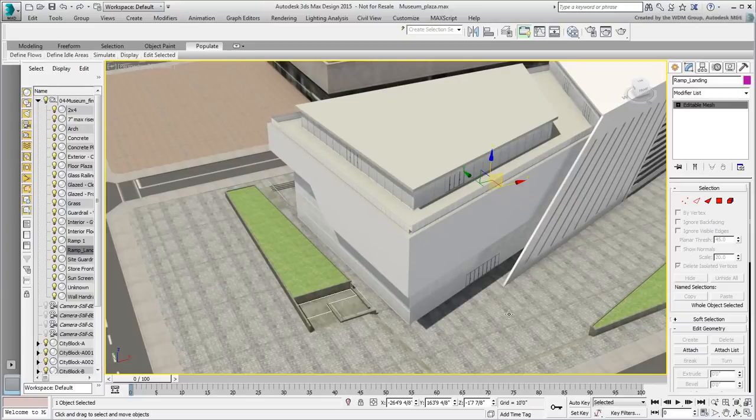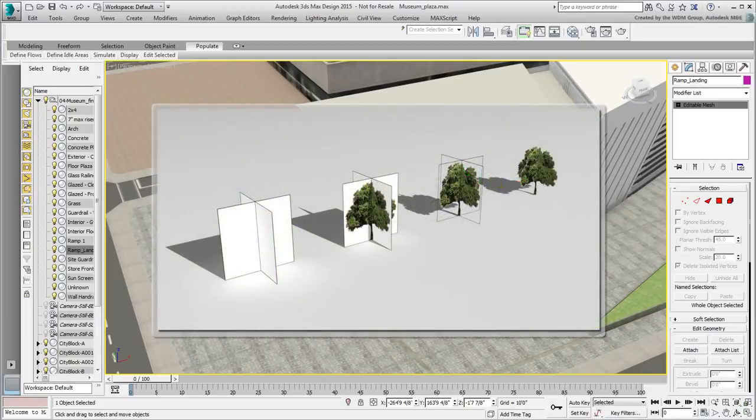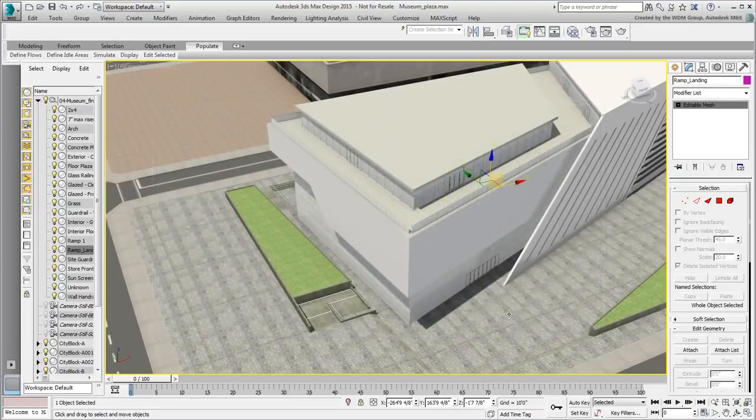In Revit, they rely on the RPC plugin that creates what is sometimes known as cardboard trees. This means it uses simple planar geometry with the image of plants or trees applied to them. It's a very effective way to scatter a lot of foliage without adding too much polygon count. Although you can use similar commercial plugins in 3ds Max, the native approach is to use 3D trees. They look quite good from all angles, but they do tend to add to the total number of poly count, so keep that in mind.